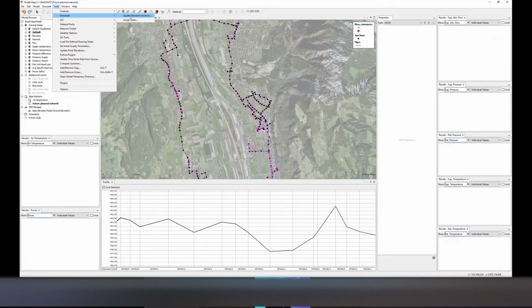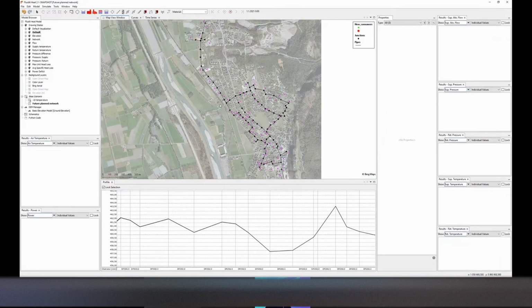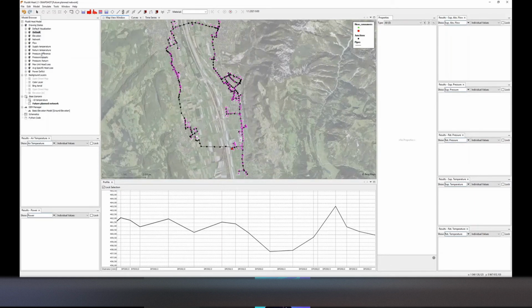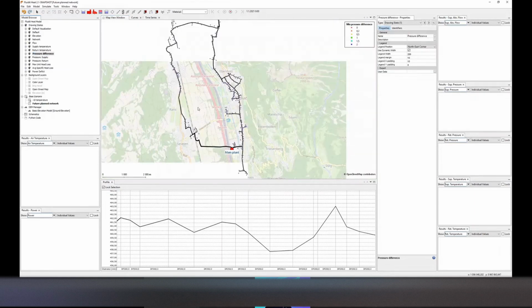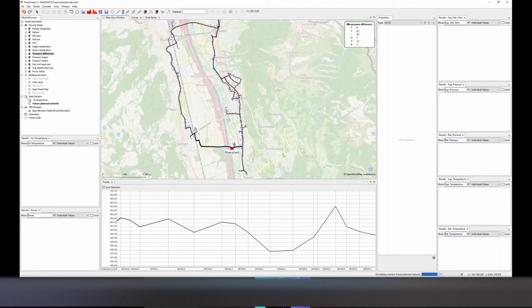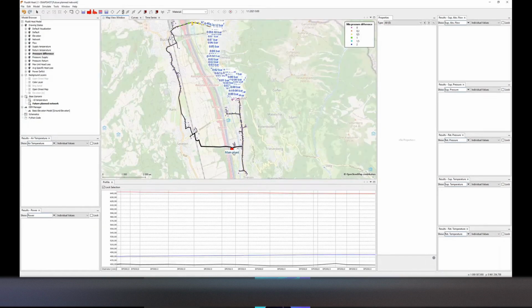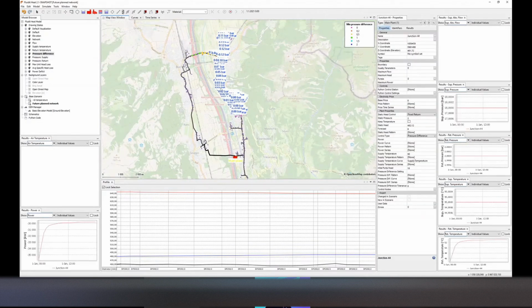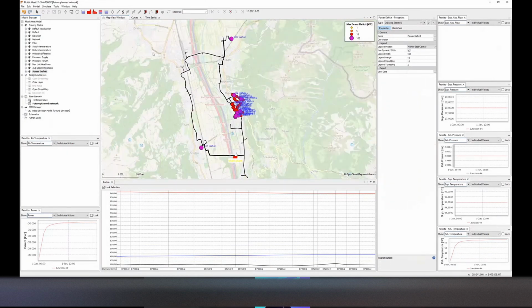Let's again update the demand junction so that they are actually connected there to the network. And we can just go ahead and then simulate to see how the network would function. So I run into quite some troubles, as the pressure difference becomes very minimal here, and there's a lot of power deficit that's happening. So power that is not being able to be brought into those consumers.